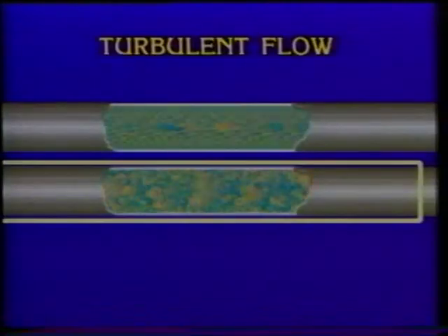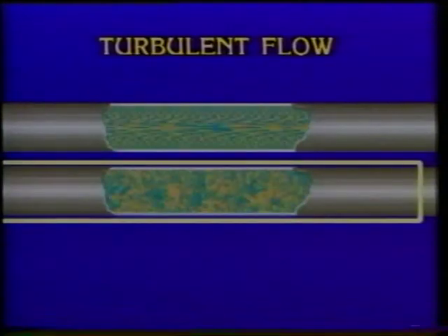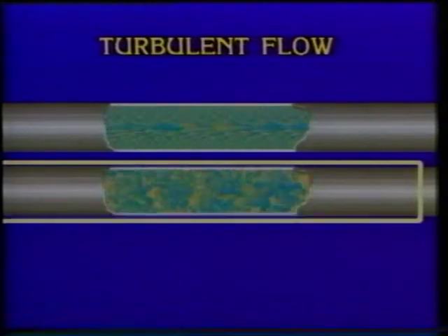This drawing illustrates a flow regime called laminar flow. Looking closer, you can see that fluid flows in parallel layers, with fluid near the center of the stream flowing much faster than fluid near the walls. If the velocity of the fluid were measured at various points across the pipe, a flow profile like this would be revealed. The second major type of fluid flow is called turbulent flow.